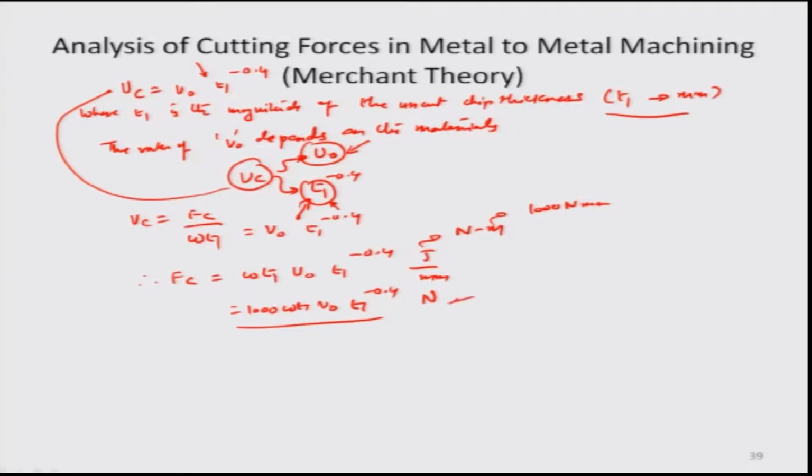So, that is how you can find out the cutting force requirements given the material property U0 of a particular material, that is, the specific energy of the material, and also the width and the depth of the cutting zone. This is very important to determine how much force would be necessary and sufficient to start removing the material. So, let us do a numerical problem example to find out how we apply the specific energy concept in cutting.